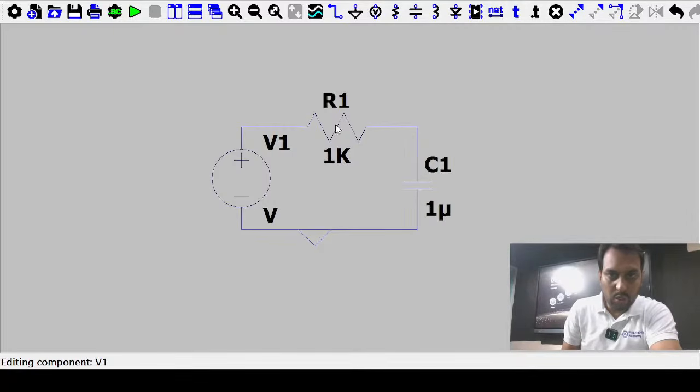So you just click on the right hand side of that voltage element, and you find DC voltage, or you have advanced, you can set the input waveform as per your requirement. We have a lot of input waveforms: pulse, sinusoidal, exponential, single frequency frequency modulation, pulse width, logic. Okay, and you can also add a pulse width logic file. You have any file simulation, so you can set it.